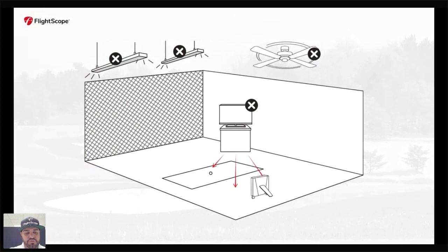However, if you do not want to remove the shot, and just want to remove it from the averages, I believe this is a function of only the PC software at the moment. You can go in and click delete, and it removes that line out of the averages. If you hit shift delete, it will remove it completely. I believe that's only a function of the FlyScope PC software. However, it is a great point, and I will ask the developers if this is something that could be added in future to our mobile applications.